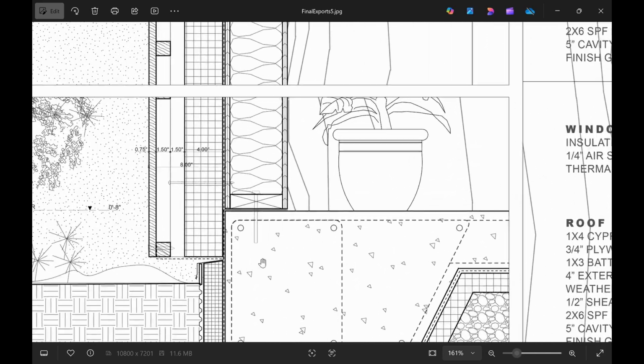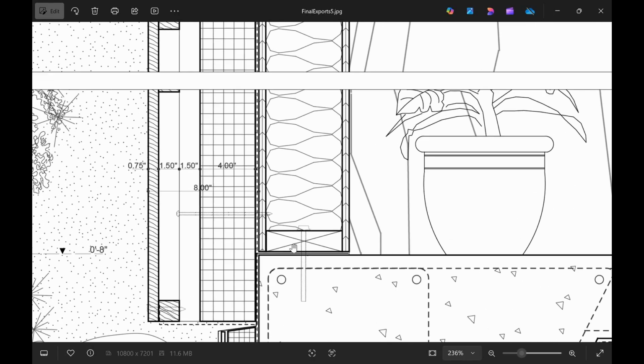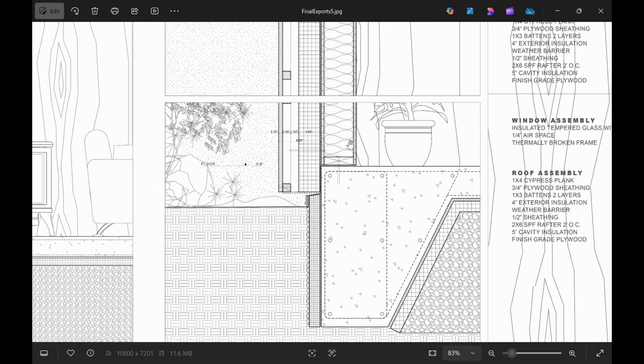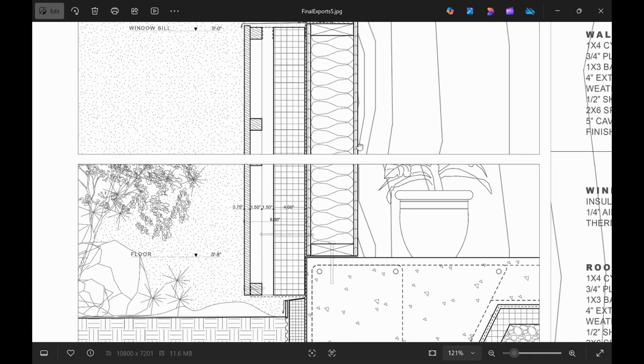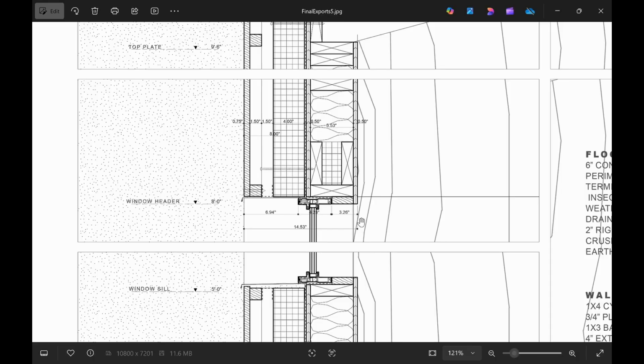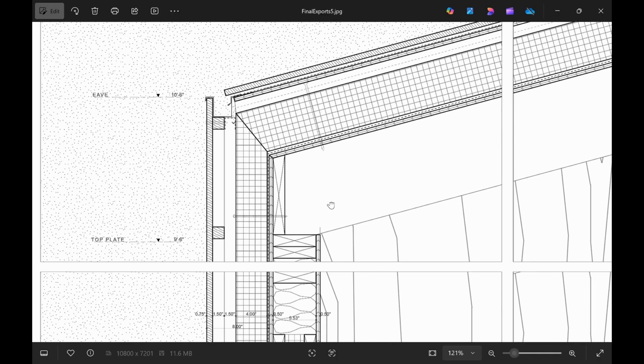But again, see, this is when I scaled it up to 1 inch. So this is like a 3-inch scale section. So we're getting very close into the details here. In reality, a 3-inch scale would read like this on your screen, this is how it would read in terms of actual scale on a screen. But because this is 300 DPI on a screen, it's going to be really zoomed out. At a 3-inch scale, you should be reading it this big on a screen. I should have pulled these out a little bit more, the lines here.